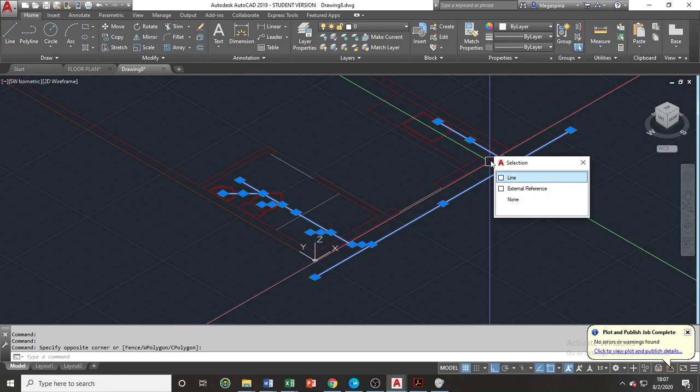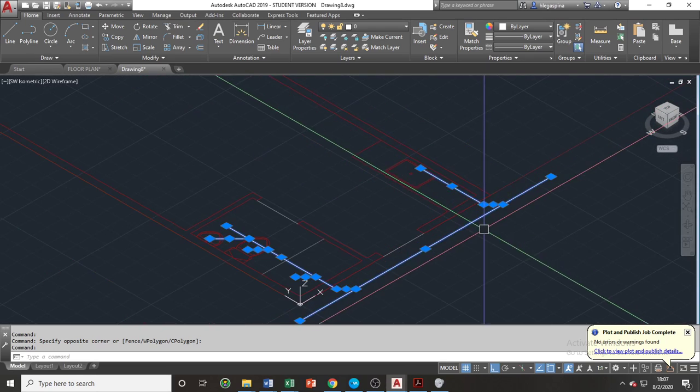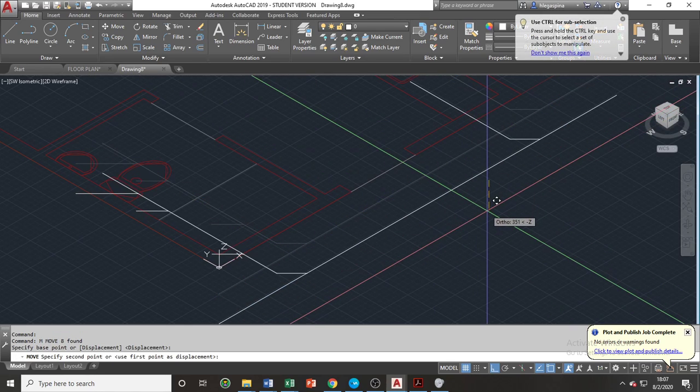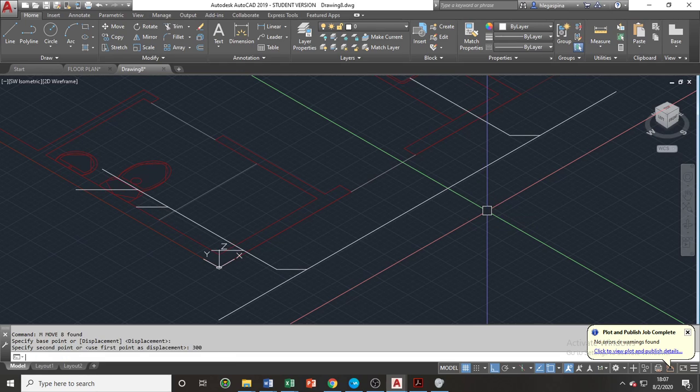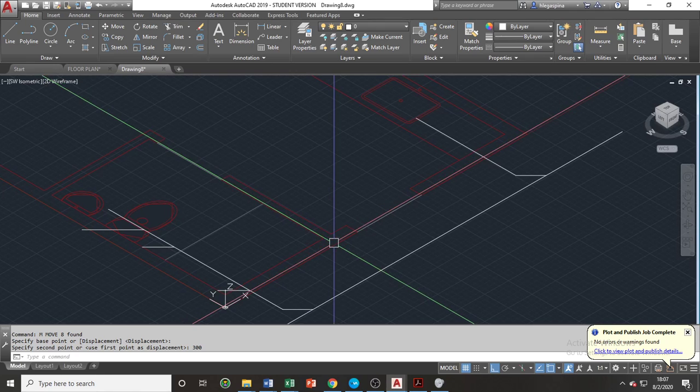So basically, sanitary pipes are located at least a foot under the floor finish, depending on the thickness of the slab. As for now, let us use 1 foot or 300 mm in metric measurements.